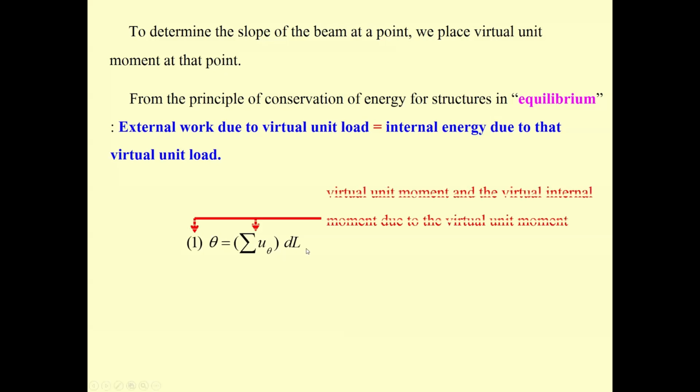Things are going to be kind of the same. We are going to apply 1 unit of force if you prefer to determine the deflection, delta or V. But if you prefer to determine the slope, the virtual unit load is going to be a virtual unit moment.